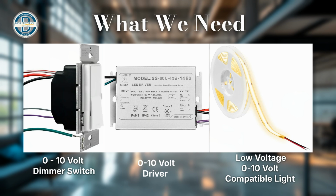Unlike other dimmers, a 0 to 10 volt dimmer has the additional 2 control cables, violet and gray, that provide the control signal to the driver, which, similar to the dimmer, also has outputs for the violet and gray control cables, unlike non-0 to 10 volt drivers. It is important to note that all devices and light fixtures must be for 0 to 10 volt dimming, or else the system will not function as intended.